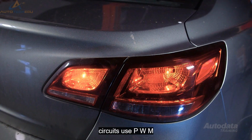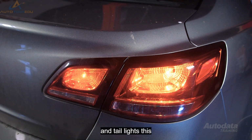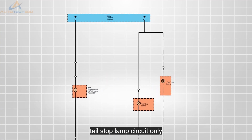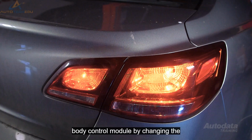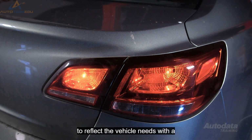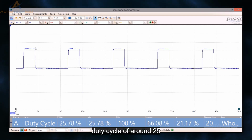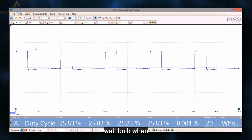Some lighting circuits use PWM control to change between brake and tail lights. This tail stop lamp circuit only has one supply from the body control module. By changing the duty cycle, we can change the light intensity to reflect the vehicle needs. With a duty cycle of around 25%, the light is only as bright as a 5-watt bulb.